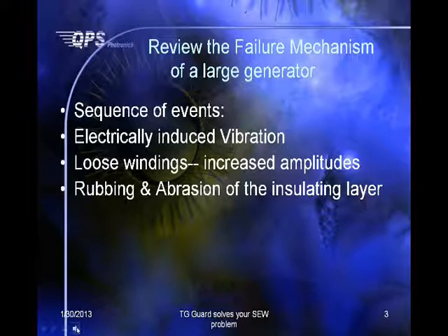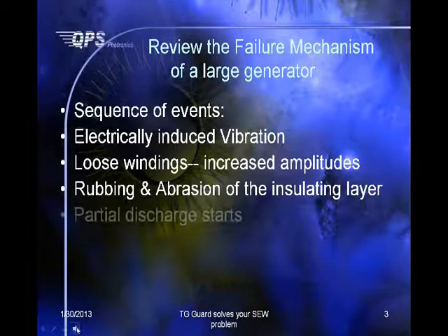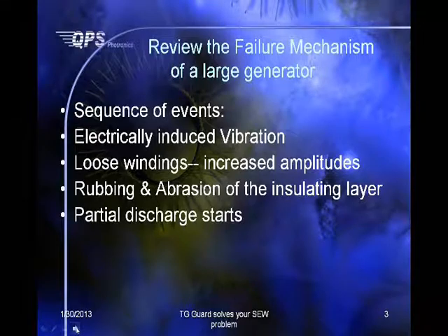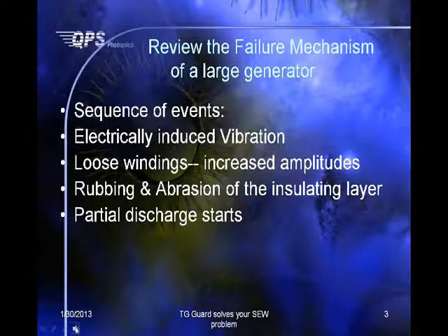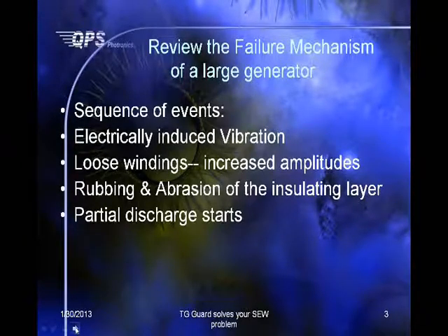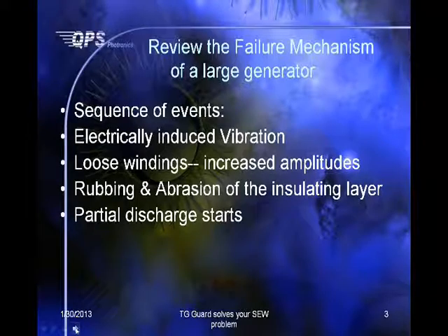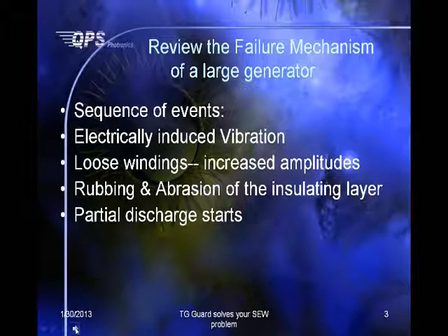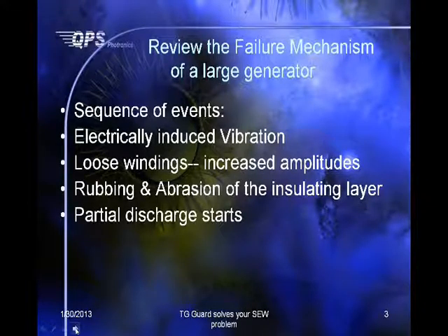Rubbing can ablate the insulating mica layer, and partial discharge occurs. You would be able to correlate the increase in vibration amplitude with the incidence of partial discharge activities.